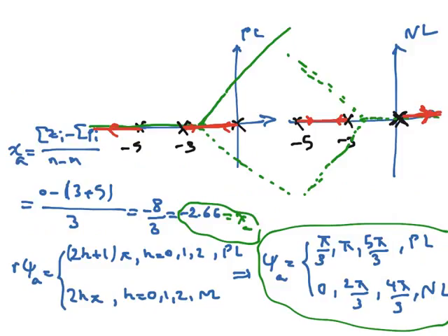If we go back to the root-locus plot on the real axis, we can see that minus 4.12 belongs to negative locus, so it is somewhere around here. And minus 1.21 belongs to the positive locus, which is somewhere around here.